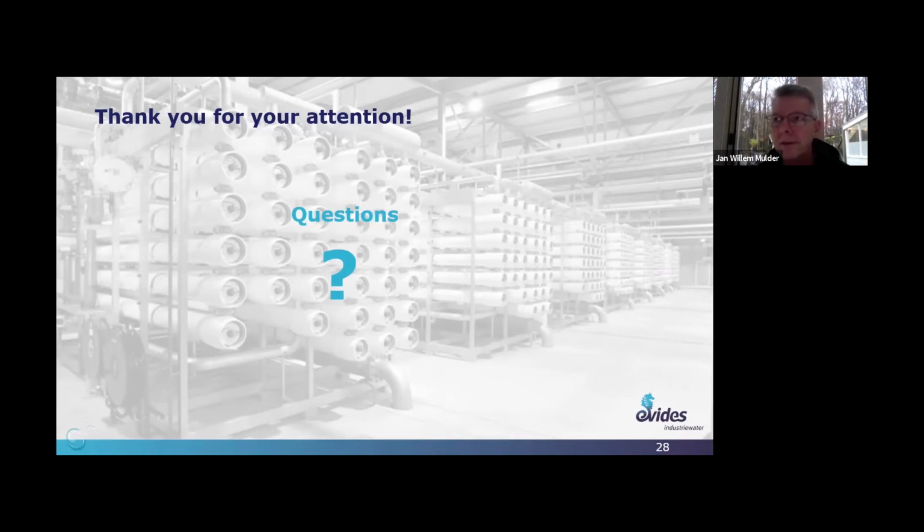We have evaporation, making use of waste heat to thicken the concentrated brine flows, to make even demi-water out of it. There's a crystallization process to recover calcium and magnesium hydroxides separately from each other. We have an EFC at the moment, also operational, to separate solid salts and water. So it's a combination of many techniques.